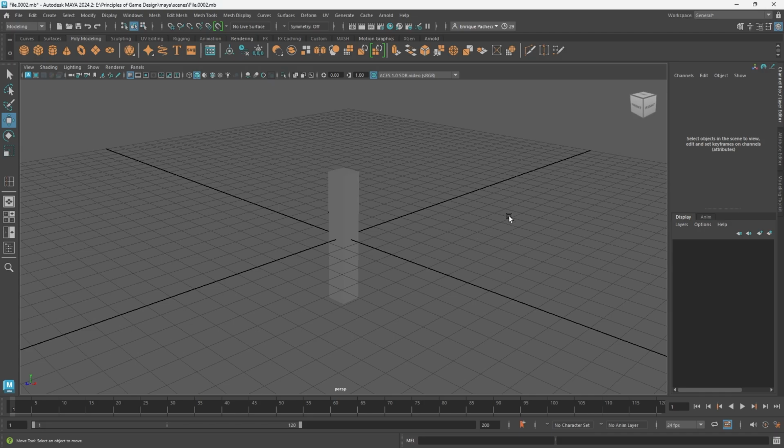One final thing I'd like to talk about is setting up Maya for rendering. So, if you look at our top left, underneath our file, we have this Modeling tab. If we click that, we can change to rigging, animation, VFX, or rendering settings. What these will do is change the menus slightly up top depending on what you are going to do. For our purposes, I'm going to go ahead and pick rendering.